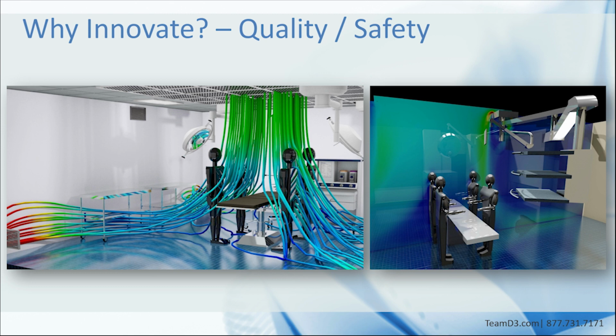Biological and chemical contaminants are always present, but controlling the contaminant exposure of occupants, surfaces, and equipment is the goal, with varying tolerance levels depending on the space. Tracking where air has been and where it is going is extremely important to medical facilities and clean rooms. They're concerned with the velocity of air near surfaces that may be contaminated, which may cause larger particles to become airborne. They want to know where a particle goes once it is airborne. Does it land on a clean surface? Or is it carried away to the floor or a collection system?